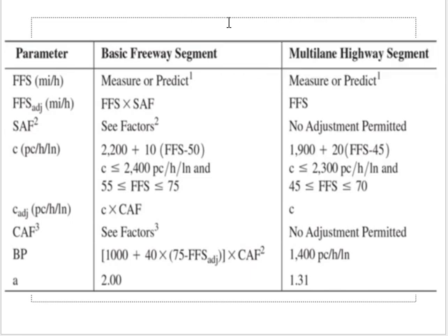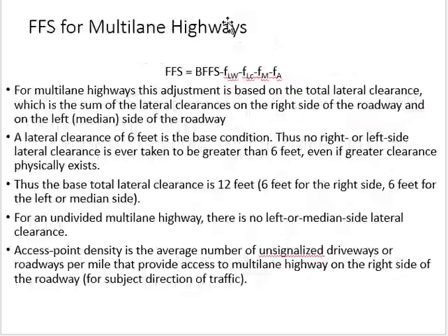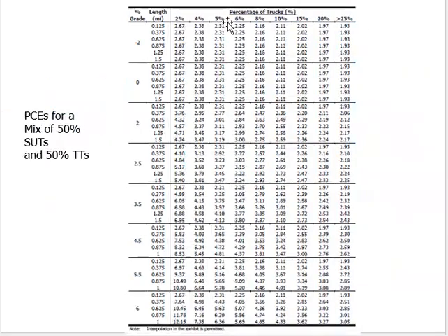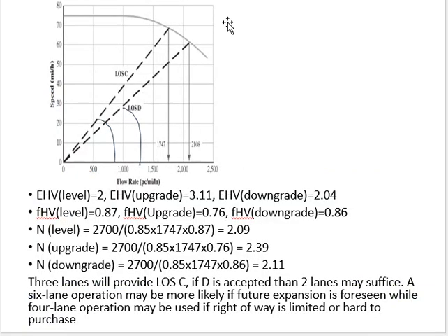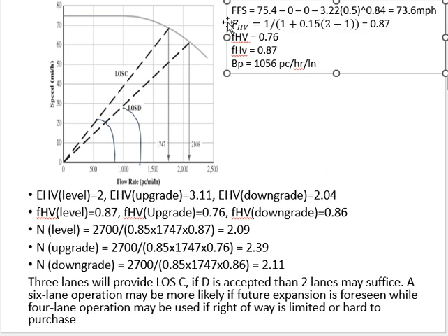So, going back to the graph, we are trying to plot the graph. From here, free flow speed, I go up to my break point. What is my break point? From here up to 1056, somewhere here there will be a straight line. I start from here, 73.6, I'll go forward up to the break point, which is 1056. There will be a straight line.